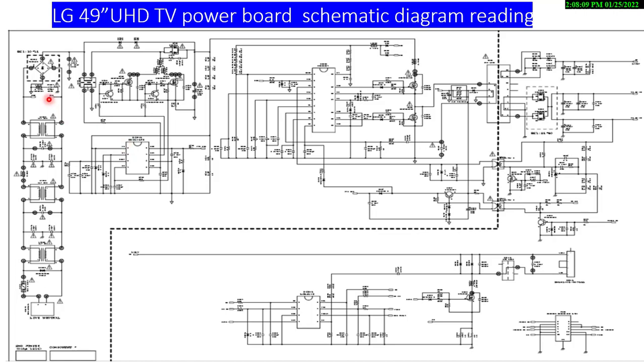The other one is, look at these pointers. Here is the arrow, which indicates the output arrow. These pointers and these pointers connect through this one. So here is a rectifier diode to convert the AC voltage to DC voltage, because at this point we have AC voltage, as this point is before the bridge rectifier. So this point is directly connected to this one, and we have AC voltage here.